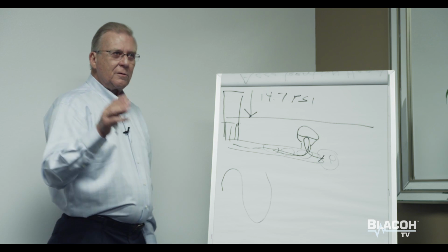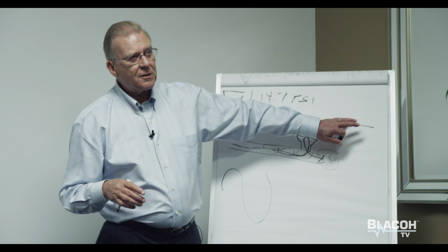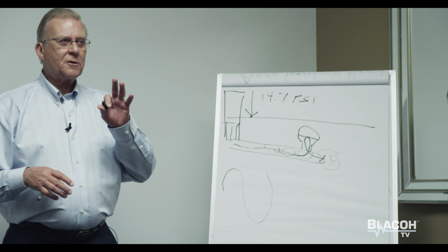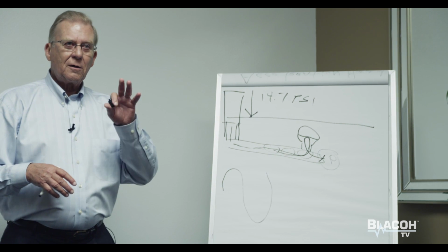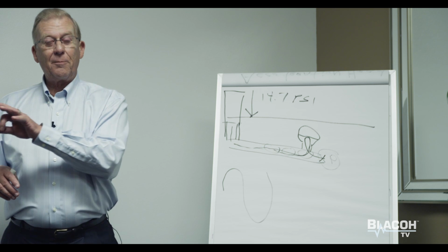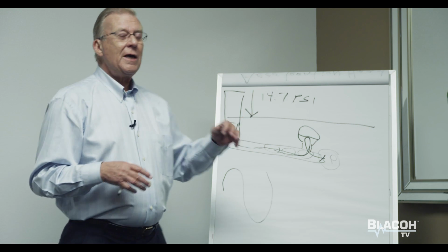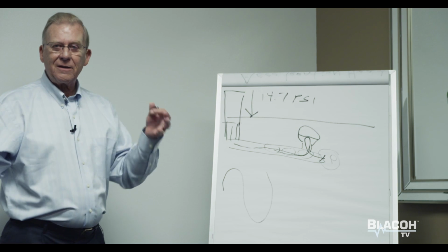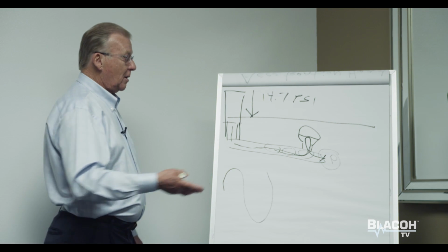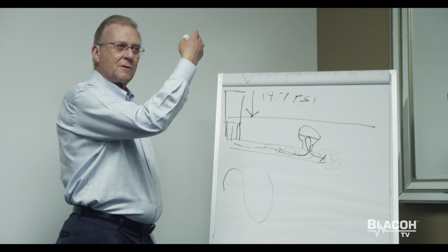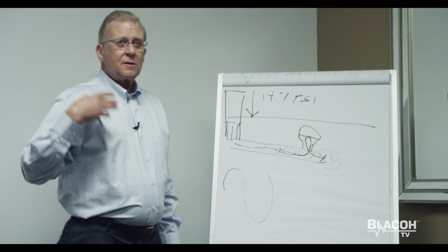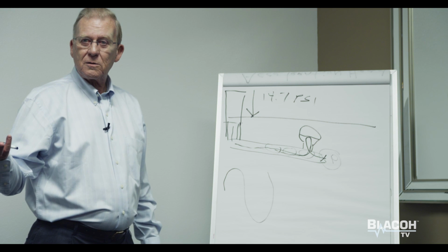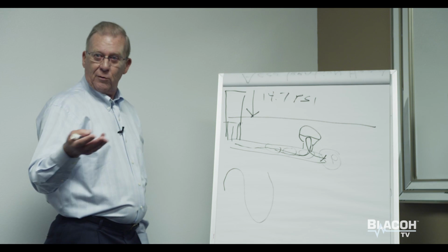If you don't use inlet stabilizers and pulsation dampeners, you can't use a key component of that formula, which is the friction loss created by the steady state flow in the pipe. So you can't use those charts. You can use acceleration head components and bring that in the equation. But with the installation of inlet stabilizers and pulsation dampeners, you can just basically go to the standard friction loss charts and use those, and they will be accurate.